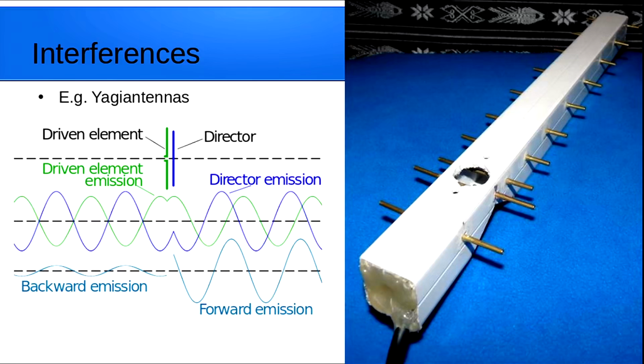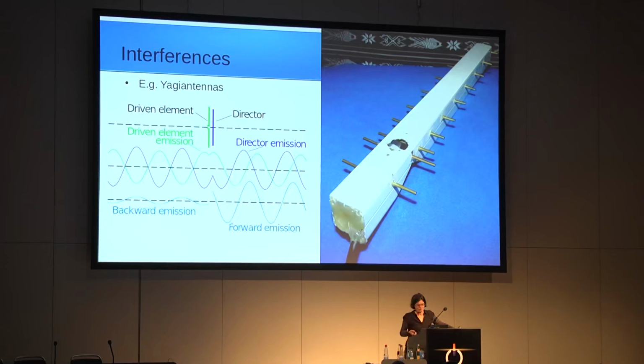The parasitic elements are receiving the signal from the driven element and at the same time also sending it out again. They are not exactly resonant, but somewhat shorter or longer than our half lambda wavelength. This creates a capacitive or inductive reactance, and this reactance modifies the phase of the element's current with respect to its excitation from the driven element.